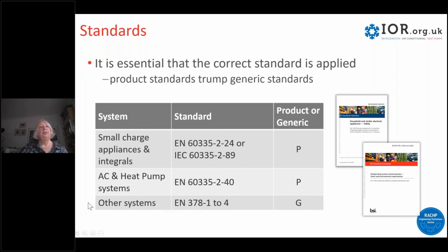Where a product standard doesn't exist, then there's a general standard EN 378 that you would need to follow. These standards are very up to date now with regard to flammable refrigerants, so the design of flammable refrigerant systems is covered very comprehensively in them.